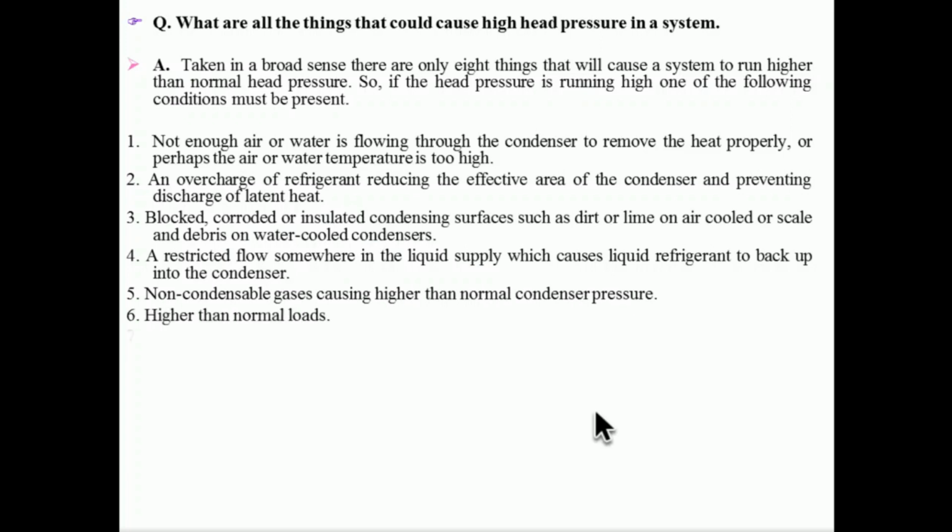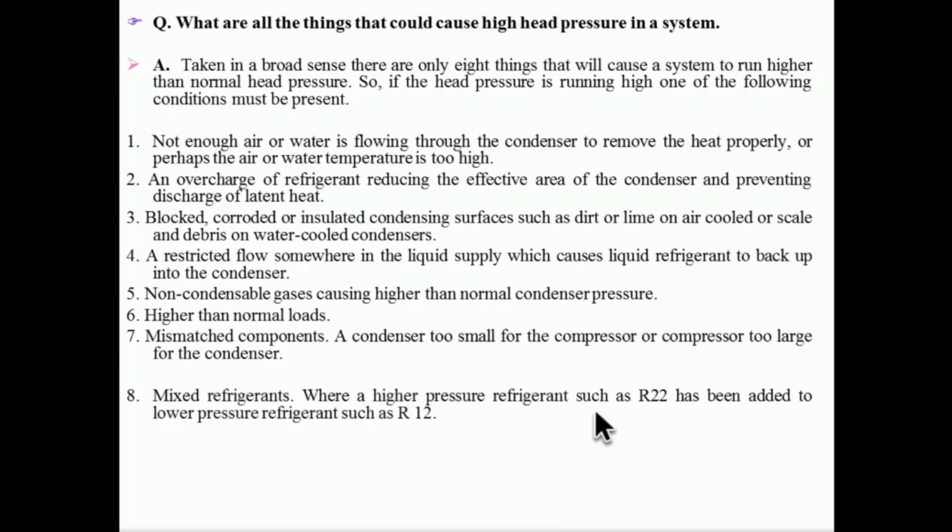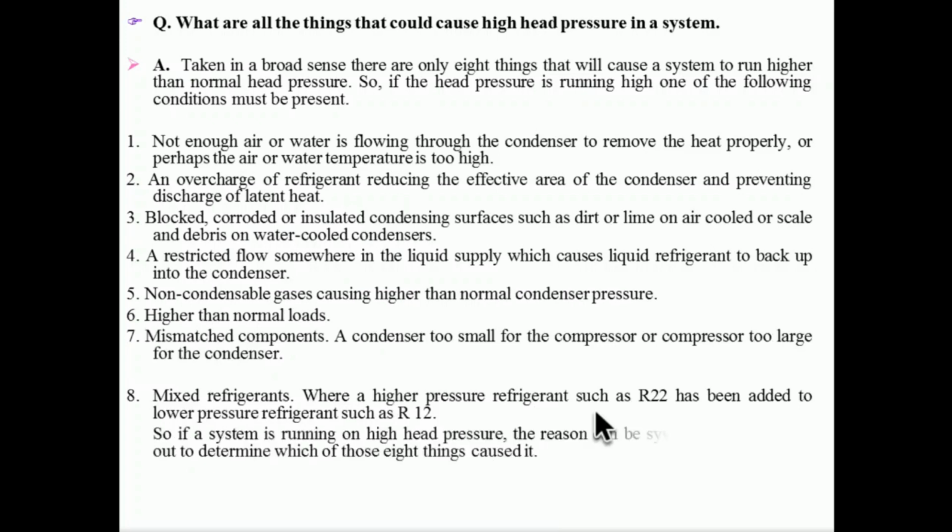Higher than normal load, yes. And mismatched components, yes. Say an undersized compressor working with a bigger evaporator is going to lead to that. Mixed refrigerant, yes, that can also lead to that.